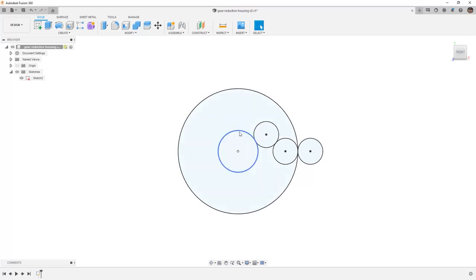We'll transfer power from the center here, moving over to our first idler gear, which will change its direction to counterclockwise. As we move to the second idler, this one will change to clockwise, and as we get to the third idler, it'll change again to counterclockwise. As this one is rotating counterclockwise, it'll rotate the large gear clockwise.